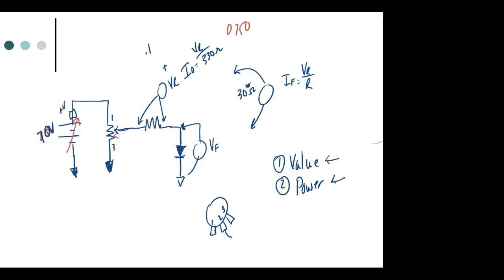So when you get out in the field and you start troubleshooting, you're not going to go out there and measure all the resistors in an amplifier circuit, right? You understand? What are you going to do? You're going to use the color-coded value. And you understand now that your calculations are perfect and your measurements are not, but they're going to be so close that you'll be able to tell if something's wrong.